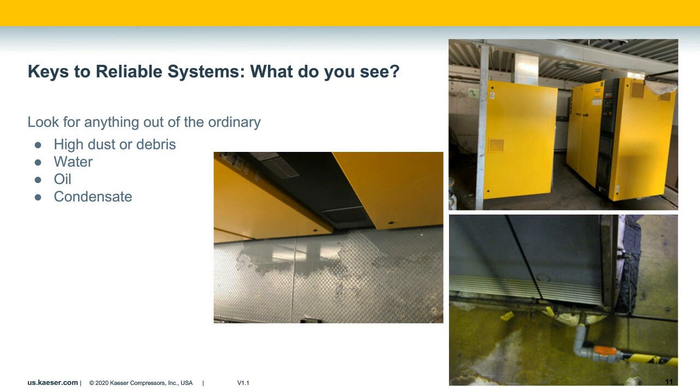Is this something else? The picture at the top right, if you look closely, you'll see a little bit of plastic on the top right, which is the electrical cabinet for this variable frequency drive compressor. What was happening, if you see the ducts coming off both of those two compressors, those ducts were not sealed at the roof line, so when we were having heavy rain, we were getting water ingressing into the compressor room and then on top of the compressor, and unfortunately for that variable frequency drive, water also got into the control cabinet and the compressor was damaged and it was down.